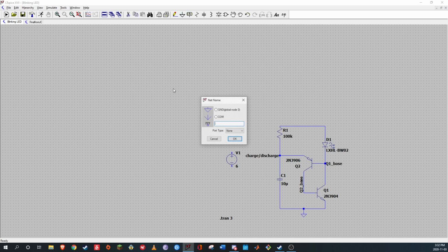And let's go to our tags. And we're gonna say, to make a port type, we're gonna say make an output. And we're just gonna call this V1, because it's voltage source 1. Actually, let's change its name to VDD. So you'll say that VDD is coming out of the positive terminal on this voltage source, and then you'll go up and you'll make another net and you'll make it an input, and you'll also call that VDD. So now these two tags are an output and an input, and you'll say, okay, I want the input to go right there.